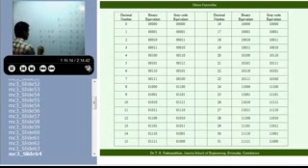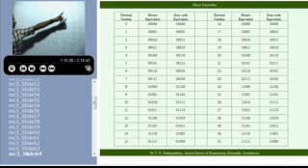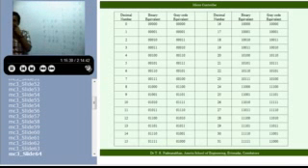If I take 6 to 7, it's a 1-bit change. If I take 7 to 8, I get here all the 4 bits changing. Unlike this, in the gray code, only 1 bit changes.